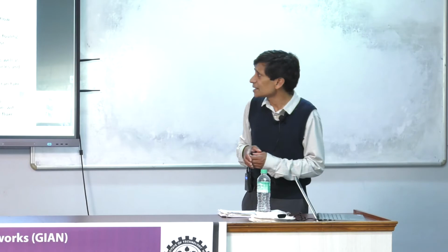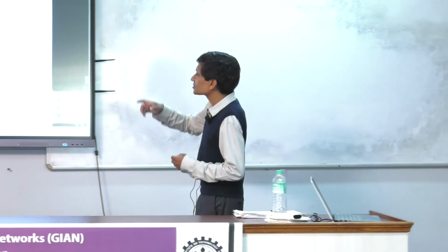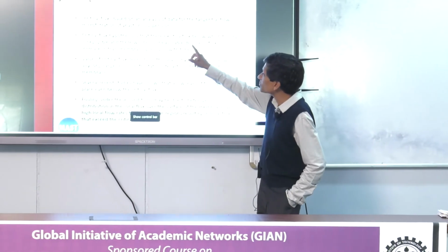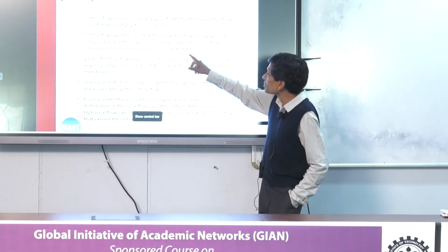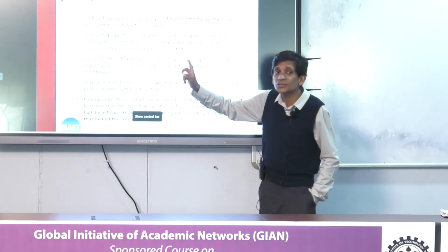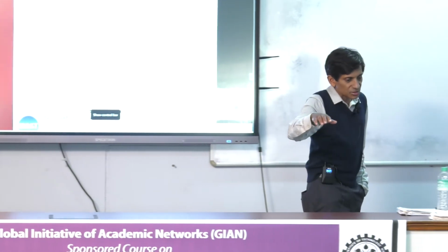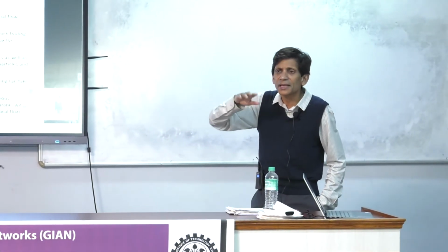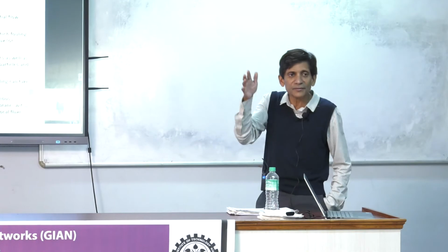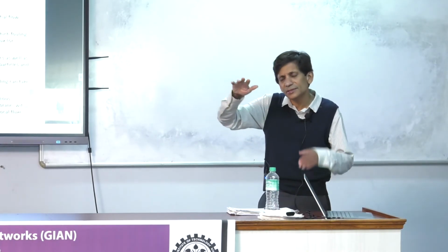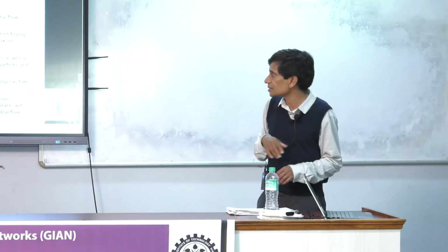They do interact. And so based on that, you come up with this critical flux hypothesis that there exists a flux below which fouling is negligible, and there will be no measurable decline in flux or increase in transmembrane pressure with time, okay? So if you run at below this flux, presumably you could run for hours and hours and hours and not see any big change. If you run above that flux, there will be some deposition and there will be a decrease, and it should reach steady state again at some point.